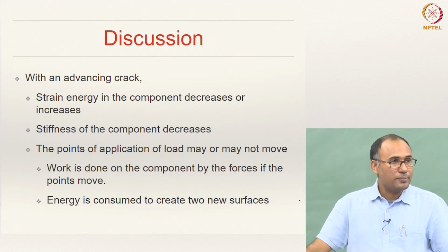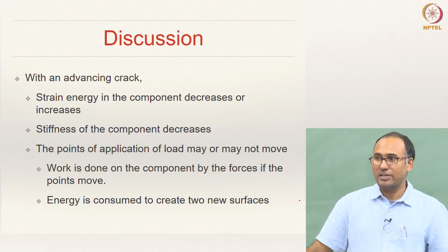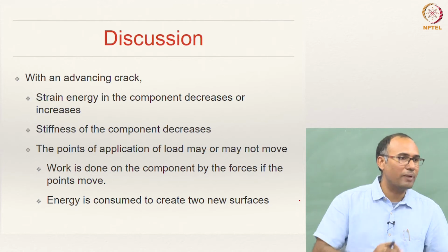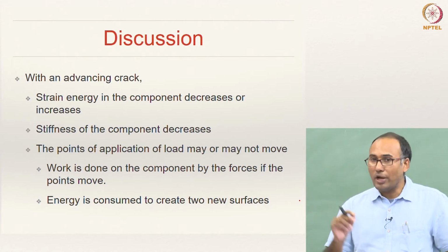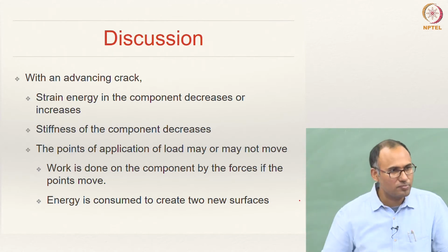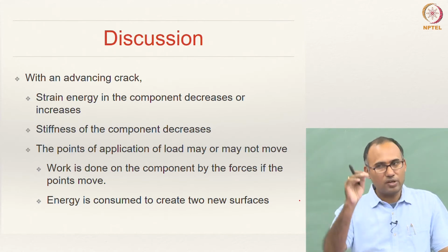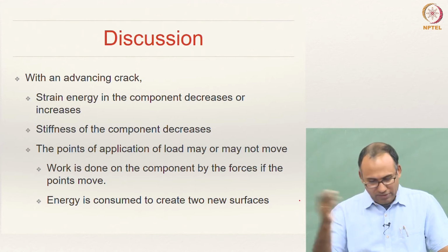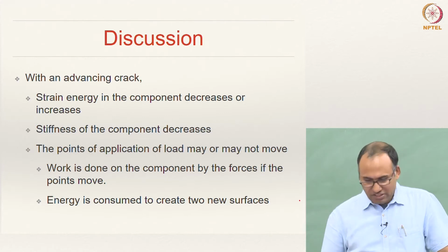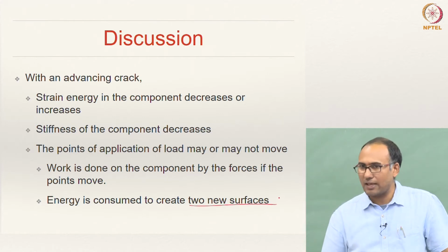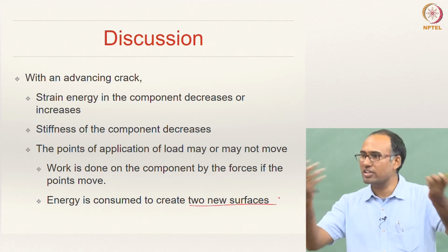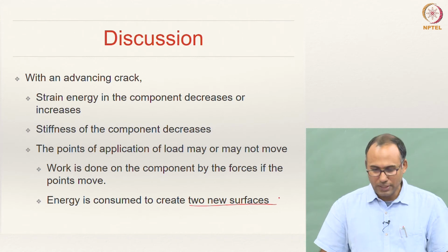That is what we mean by stiffness. And sometimes the point of application of the load can move or remain fixed. When the point of application of the load is moving, that means work is done on the system. Sometimes the point of application of load does not move, then there is no work done. And of course, when we are generating two new surfaces, that is the creation of the crack, you are consuming some energy. That energy must be coming either from the strain energy or the external work done, or both.